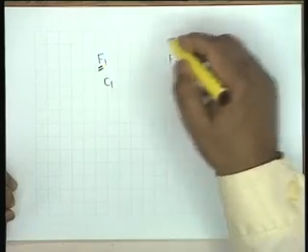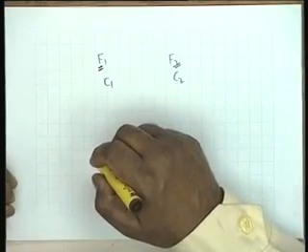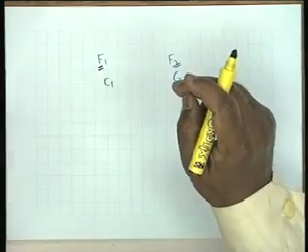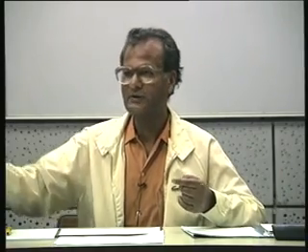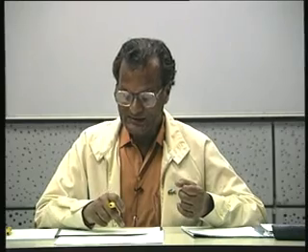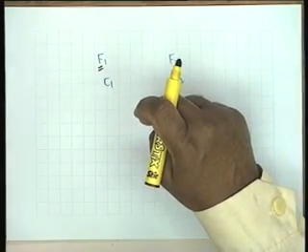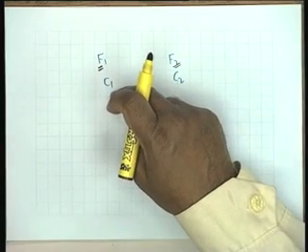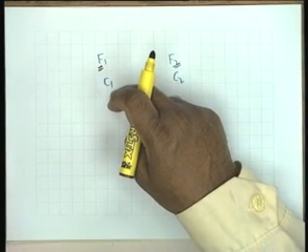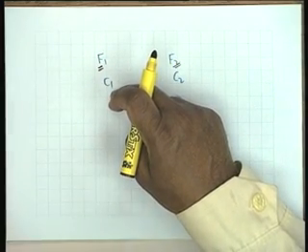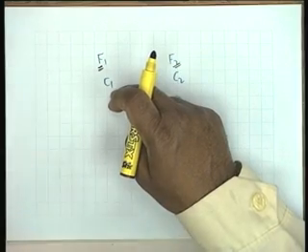We have already shown why F1 and F2 are canonic, because the number of elements is equal to the total number of specs, that is omega 1, omega 2, etc., and the residues. Okay. How do we claim that C1 and C2 are also canonic? The reason is that every time we are removing a pole, we are reducing the degree of the numerator or denominator by 1.